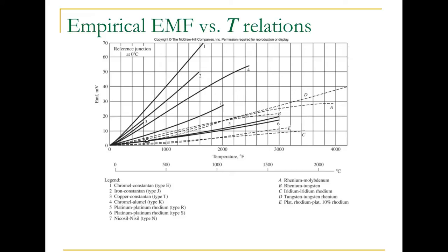So you can get other materials for different types of thermocouples that have a greater range, so they might be more expensive because the metals are more expensive. Or you could get cheaper materials. Different thermocouples have different sensitivity, so that is the relative change in voltage with respect to change in temperature. So there are different considerations when using different thermocouples, and some have chemical reactions to materials they come in contact with, whereas some metals are less reactive.